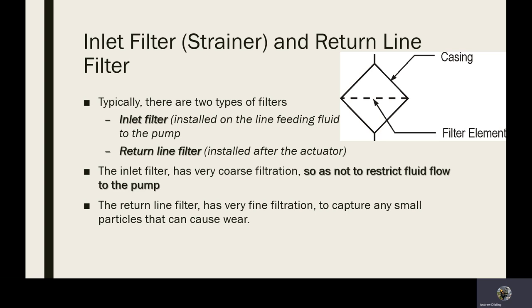Okay. Now, the inlet filter's job is not to provide very much filtration. It's designed to keep stuff out of the pump. So if there's any larger pieces of metal or anything like that that could get into the pump or into the pressure relief valve or into the sensitive bits that are coming right out of the gate, it makes sure that it doesn't get in there.